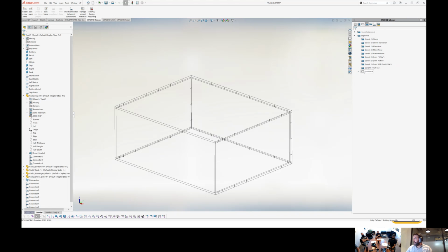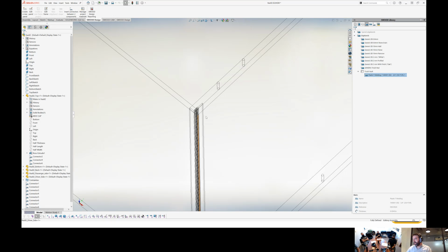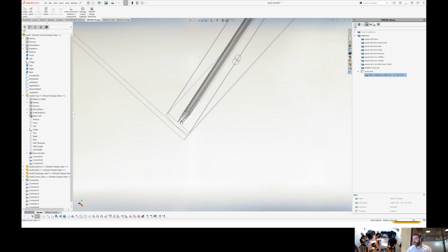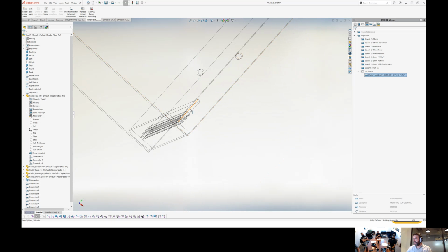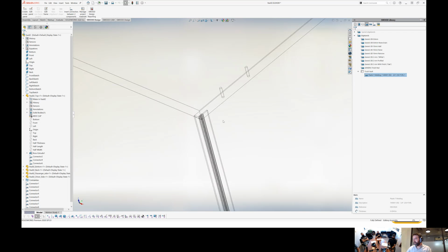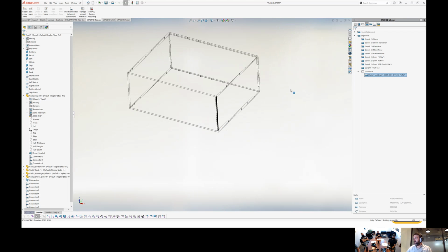Regarding the edge bands, we have the same thing, and we are able to bring in the edge band different profiles and different machining that can be processed on the edge bander. And for example, here I can just drag on my edge, and that's going to insert my edge band with my profile and directly create the groove at the same time. So I can drag and drop.